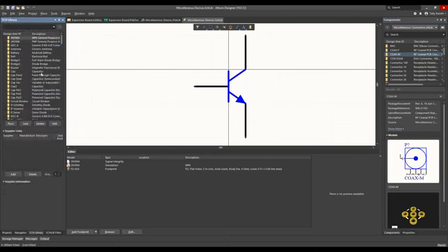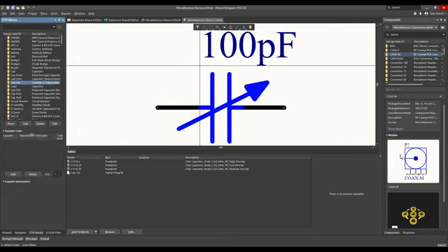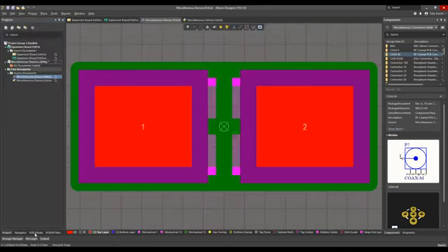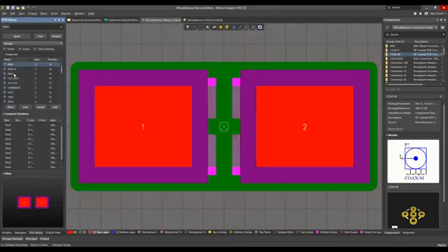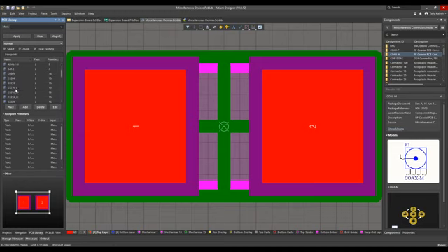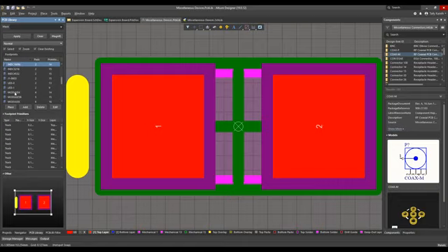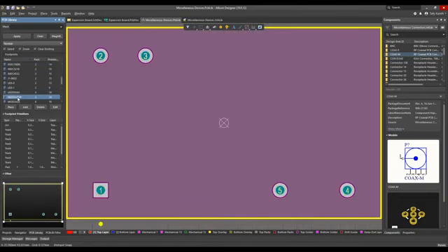They are both required for a component to be used for design capture and placement on the PCB. The schematic library holds a symbol used for design capture. The PCB library holds the footprints that are used on the PCB when placing the components. These can be compiled into an integrated library. That is a single file with the extension of intlib. We will use the default installed integrated libraries for some of our design capture.